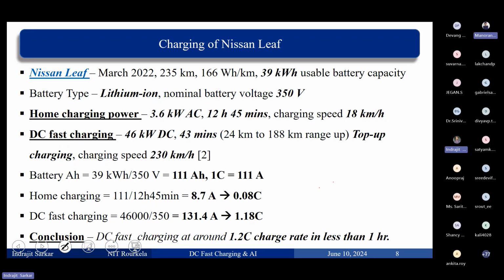Why? Because when you start charging this vehicle, that time the grid is already overloaded with the night loads. Various lighting loads, TVs, everything is working. At that time you are putting the vehicle on charge. What is the harm? There are several people going to charge the vehicle from the grid, and that is going to create a peak overload on the grid. So you are loading the grid starting from 8 p.m. The grid has to take care of it.